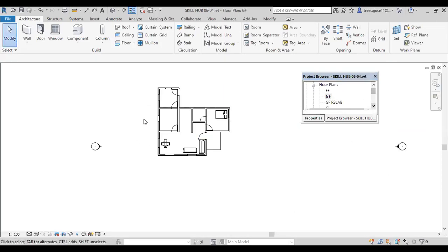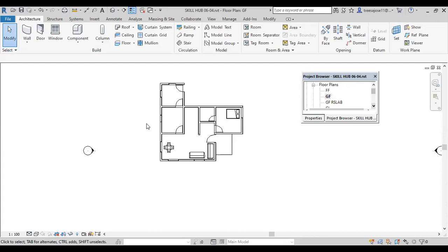Then I need to show the section of a particular position. I need the vertical difference and what type of footing details we are creating. All the vertical distances we need to show in a different view. In the project browser, you have to create a section line first. Then only can we generate the view.